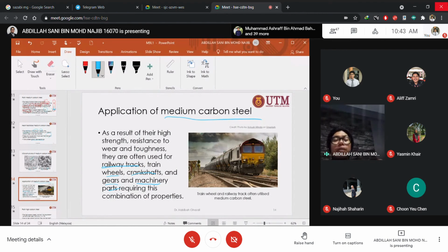So this structure is hard on the outside, soft or ductile on the inside. So against friction, it is good, and also it is not exposed to brittle fracture because we have sufficient ductility.